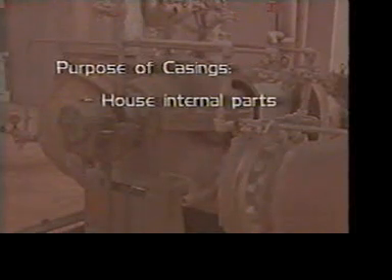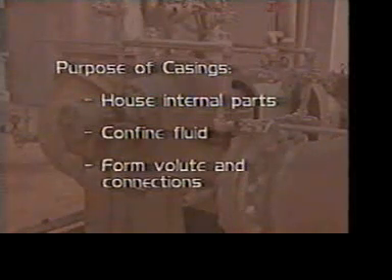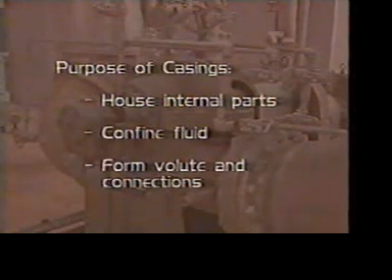They house the internal parts, keeping them in the proper position and protecting them as well. They confine the fluid being pumped and direct its flow. And finally, they form the volute and connection points for suction and discharge piping. Pump casings have 2 designs, solid or split.